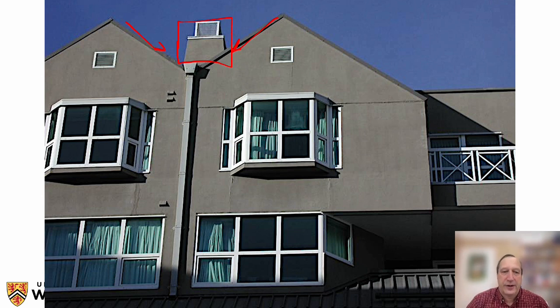And then you'll notice here, this low-slope flat chunk that sticks out. Notice how much overhang? Well, maybe about 1.5 inches here and exactly 0 inches here. So rainwater is going to be plastering up here because it's going to be deposited heavily, run down to this projecting bay window, which is not pitched and does not have a drip edge.